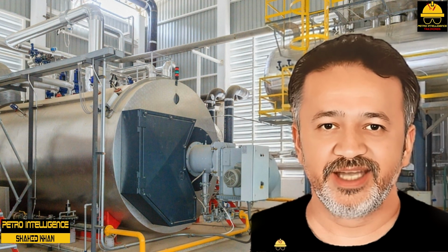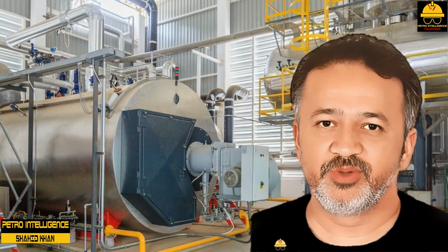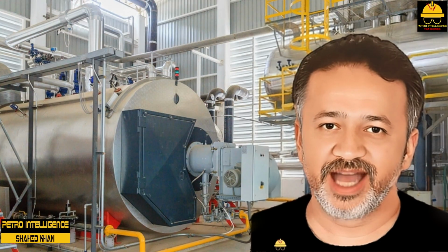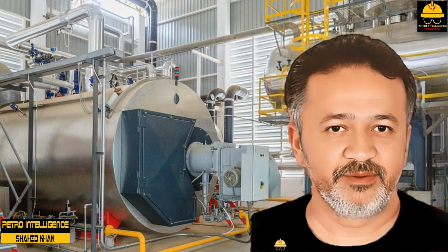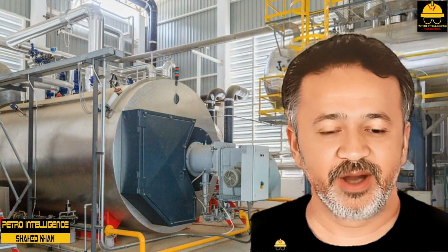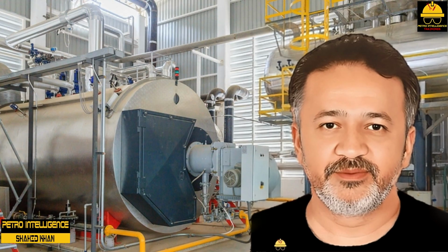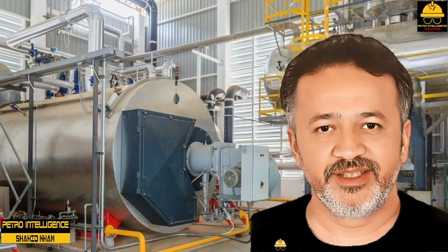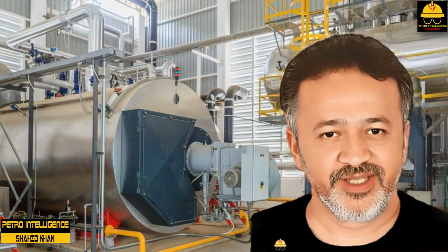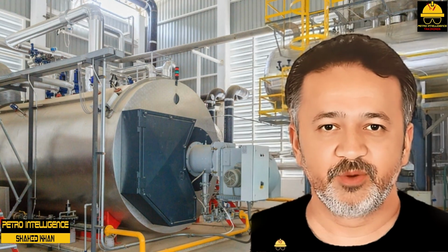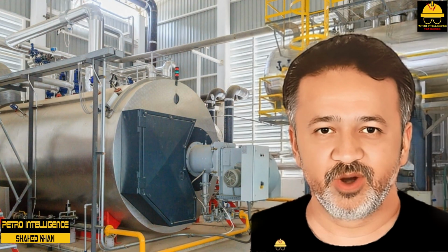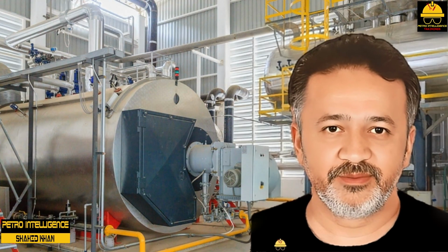Steam systems designed to reclaim steam use steam traps to remove condensate. Steam traps are grouped into two categories: mechanical, inverted bucket steam trap and float steam trap, and thermostatic. Thermostatic steam traps are cheaper and selected more frequently than any other. They respond to the temperature differences between condensate and steam. A common thermostatic trap design is the bellows trap.